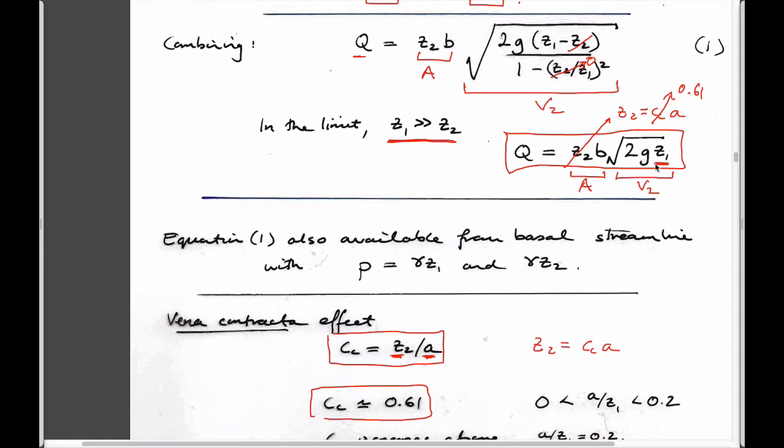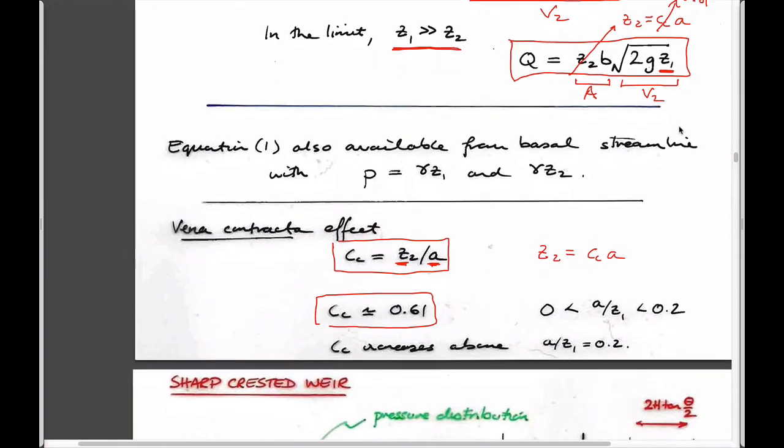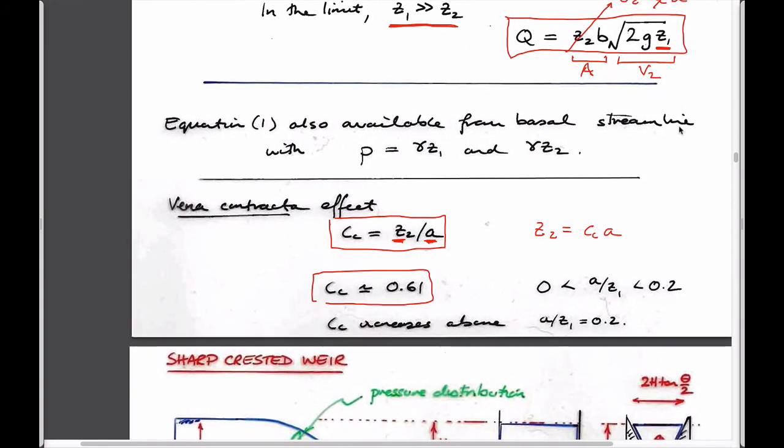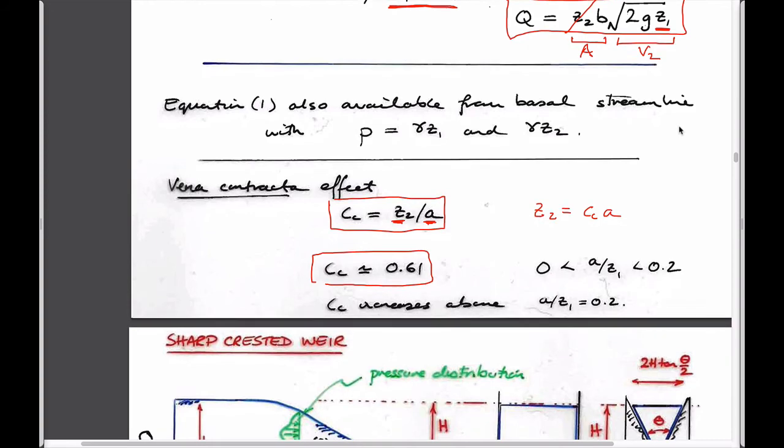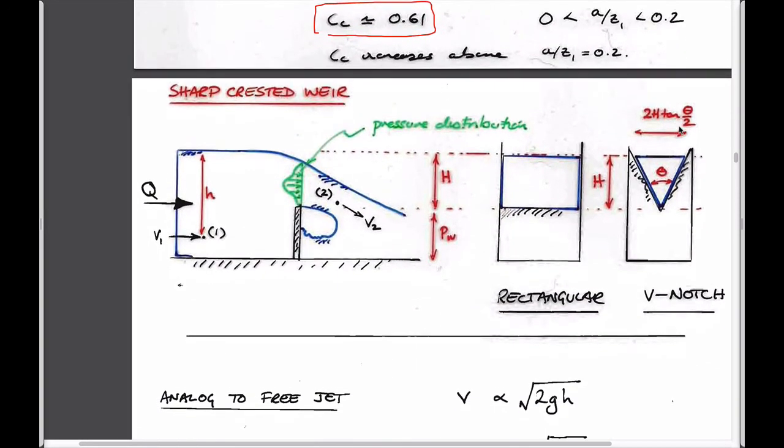You just measure the upstream depth, water gauge. You don't care about measuring the downstream depth, but you just know the geometry of your dam, and you get it straight from there. So that's, I guess, the relevance of doing that. Yeah, you can save yourself some work.